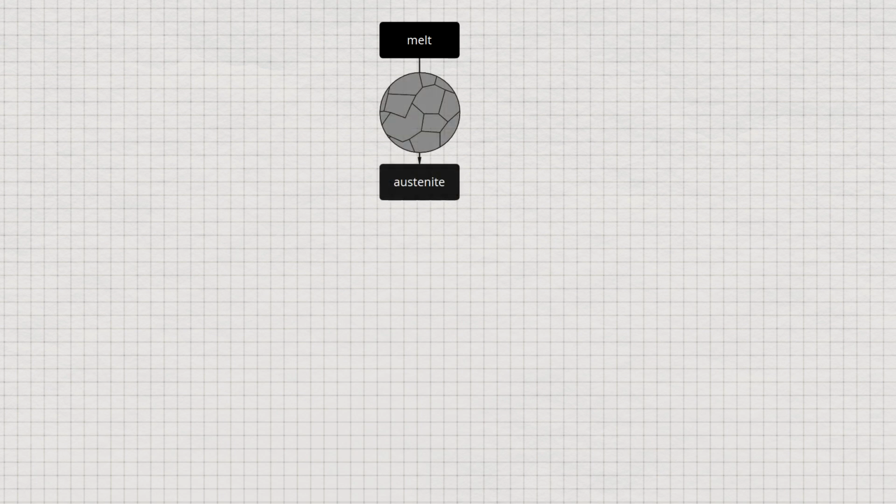Let us summarize the microstructure formation of steels once again at this point. The actual solidification process in steels takes place independently of the carbon content, as in a solid solution alloy. Austenite is first formed from the melt. In the face-centered cubic gamma iron of austenite, the carbon is completely soluble after solidification. All further microstructural processes now take place in the solidified state.